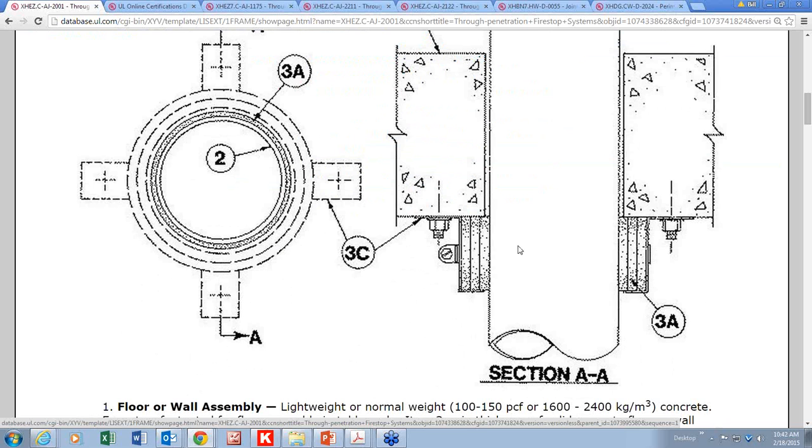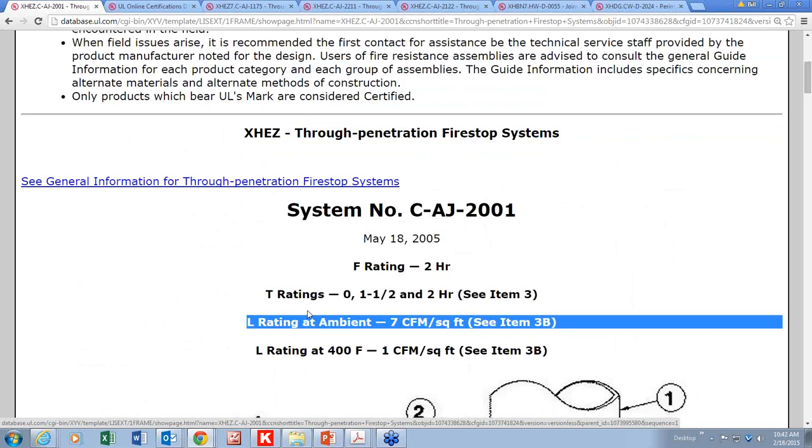This one's a plastic pipe. It's got 3 wrap strips around the perimeter of the pipe. They're all butt wrapped, not spiral wrapped, as you can see here, because there's no spaces. And then metal banding is used, as well as metal collars to hold it in place, with the collars bent at 90-degree angles, so that the intumescent wrap strip expands into the pipe, providing an insulating char for 1, 2, 3 hours, whatever the system is.